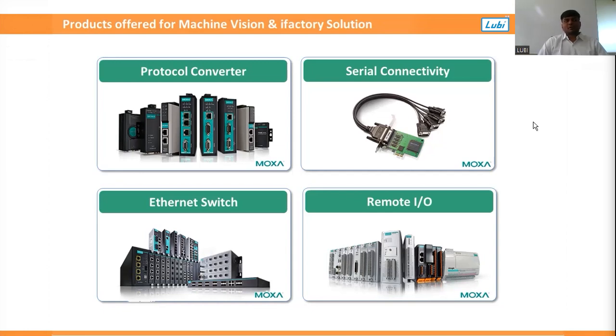We have some remote IO modules in our basket. Modbus RS485 based, Ethernet IP and Profinet based remote IO modules are there. DIDO, AI, multifunction remote IO modules are there. If in any application a PLC is not required and only some IOs have to be monitored, then this type of remote IO module is useful. In remote IO modules with Modbus TCP/IP, we have 2 ports. If any customers want looping or anything, it is also possible for redundancy applications.